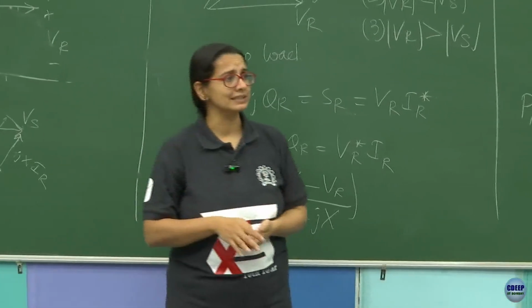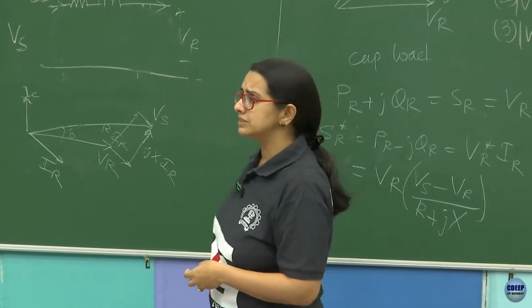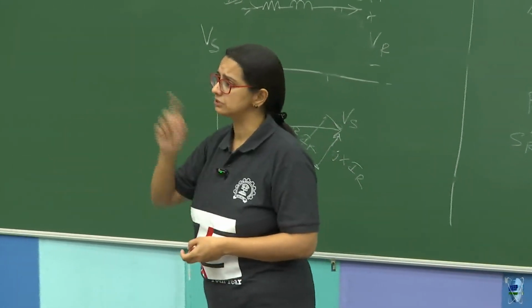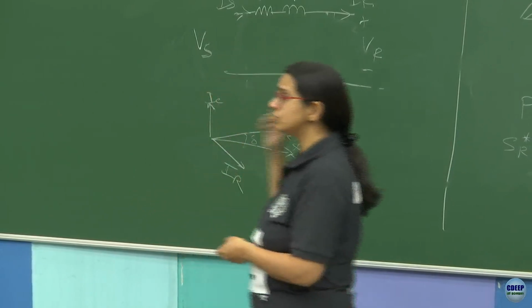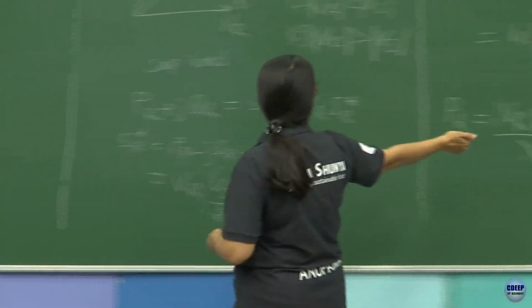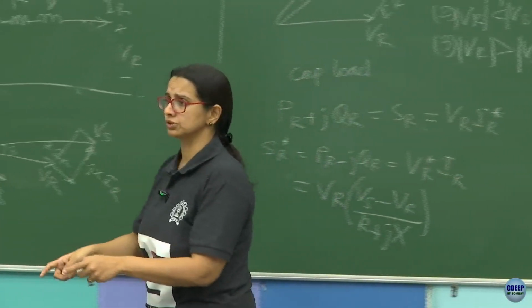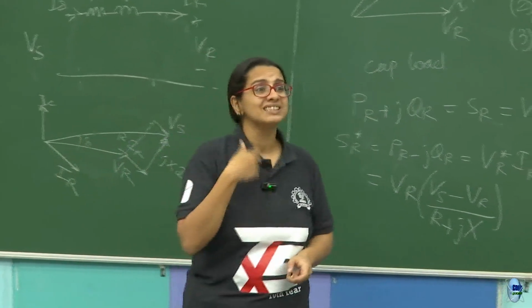This is of course necessary, and you need to figure out when you're doing trades how all of this is going to play out. Do you in fact require reactive power compensation or not? Are you going to require a voltage correction? Because if you don't do any voltage correction, it will manifest as a limitation on how much power you can push. Make sense?